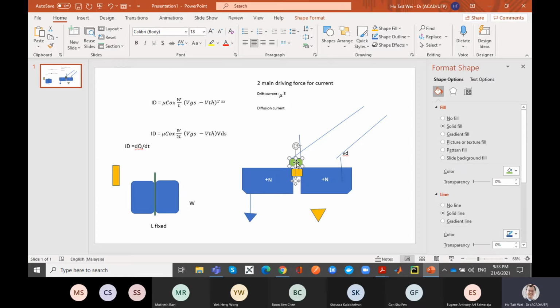Long time ago, it used to be metal. Now this is a silicide. It's a form of silicon, a type of silicon. This also has free electrons here. So whenever I have two conductors with free electrons, that is the definition of capacitance, right? So I actually have a capacitance from this node to this node. This is called the depletion, the junction capacitance, the parasitic capacitance. I also have a capacitance from this node to this node.